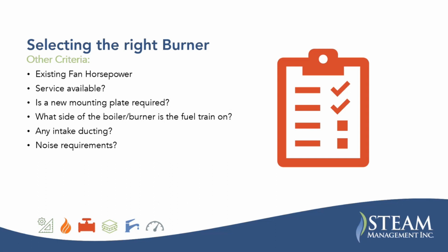And you're still always going to have problems at some point. Is a new mounting plate required? Unless you're doing the same manufacturer and the mounting hole dimensions or mounting bolt dimensions are exactly the same, the burner throat and everything is the same, you're going to need a new mounting plate or some sort of modifications to the mounting hardware.